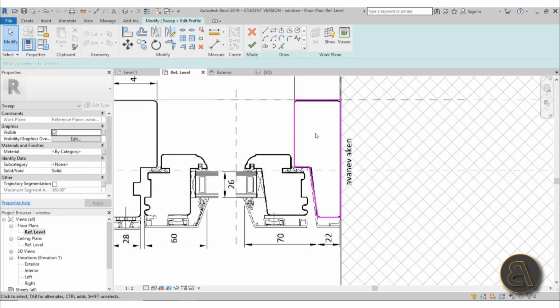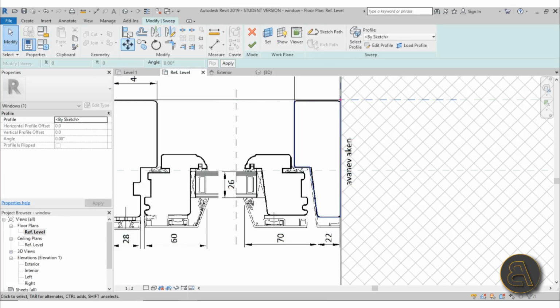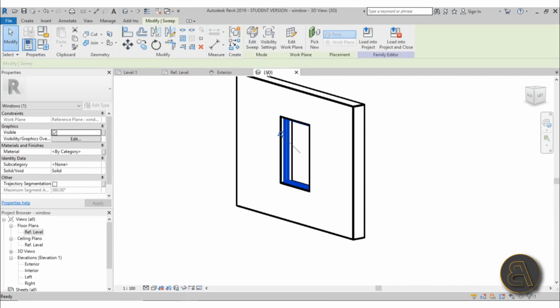And I know you're probably thinking about all of these window profiles, especially the new ones. They all have elaborate inside chamber designs, and I'm going to be talking about those designs a bit later. But for now, for strict geometry, you want to keep it simple. So only simple shapes like this one, no holes inside, no voids. We're going to be talking about that a bit later on, and it's easy to create, and it's just going to bring the whole size of the model down. It's going to be easier on Revit when you're using it. So just hit finish and go into 3D, hit finish again, and there we go.